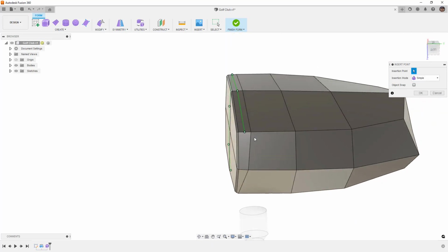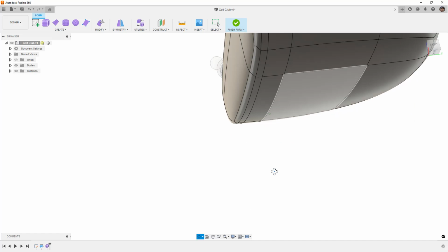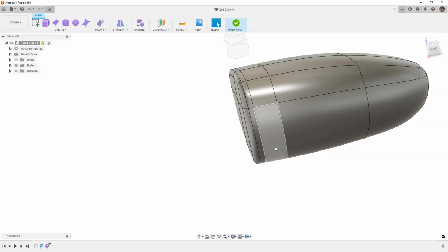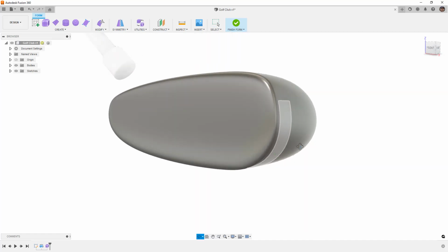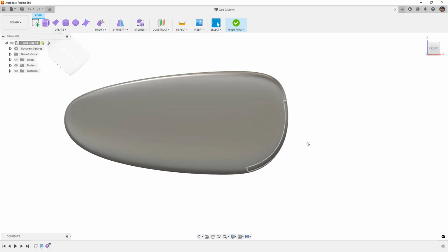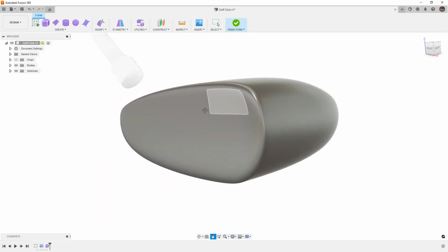We're retopologizing this, and then I'm going to come back to that point, double click this and hit delete, and then I'm going to take a look at it in smooth display. And again, Control and 4, I'm going to hide my edges. So now that transition is tighter at the top. You can see right here it's tighter, and then it sort of gets smoother on the outside.